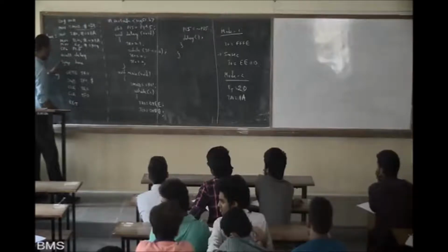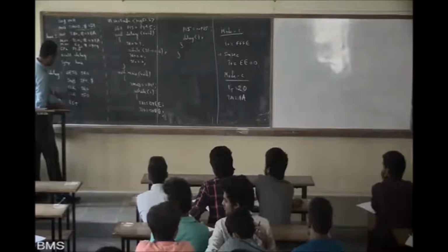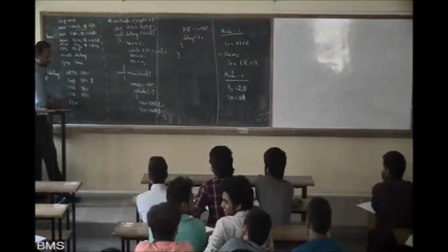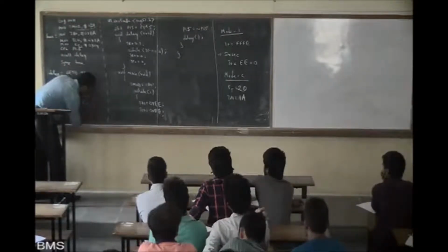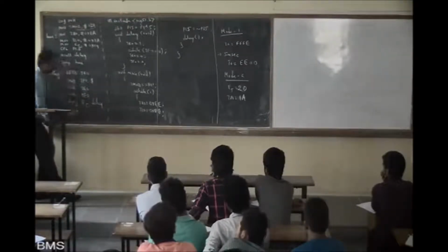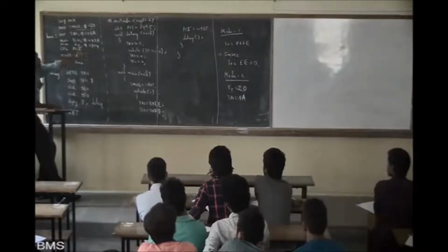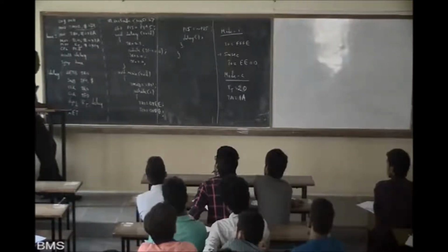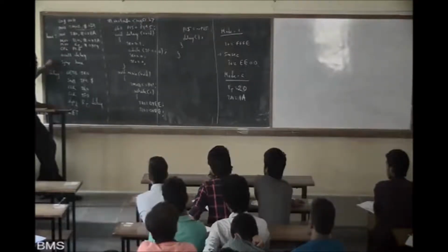After that we have CPL, call delay, then SETB TR0 here, and CLR TF0. Now in here what should I write? DJNZ R5, delay. Then RET. This will jump back here till what time? 20 times. Once it finishes 20 times, it then returns back to SJMP here.